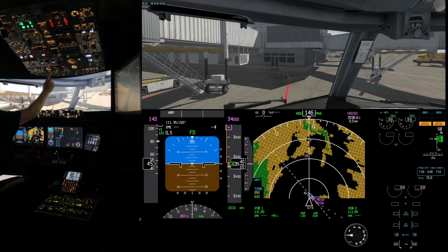So the low pressure light comes on, and then the needle for the exhaust gas temperature coming out of the APU starts to rise, which tells me the engine is starting in the back of the plane. So we'll wait for that to go up, and it'll settle down. It'll come back down once it's stabilized.